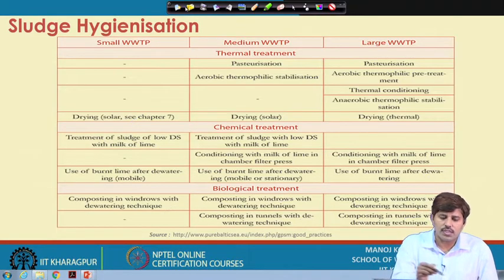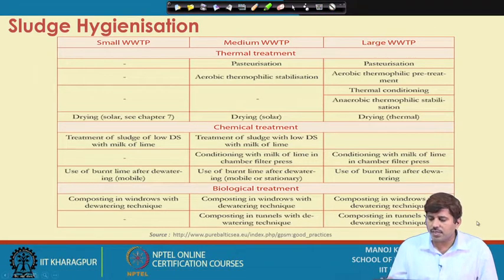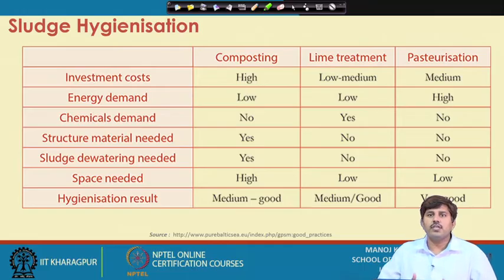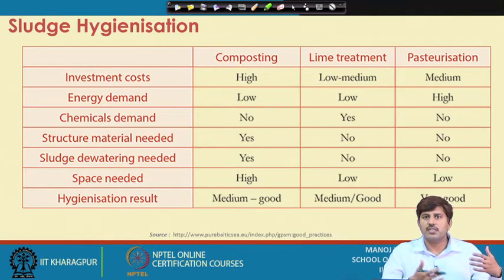Composting can be done as standalone composting, or it can be done as co-composting, where we compost this sludge with the municipal solid waste. For composting we will probably need to add some organic matter, because the digested sludge has already lost quite a bit of its organic matter.